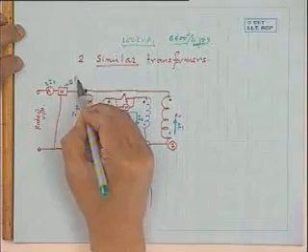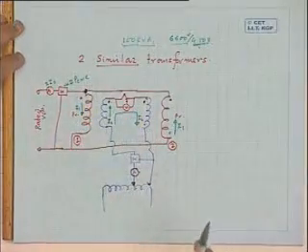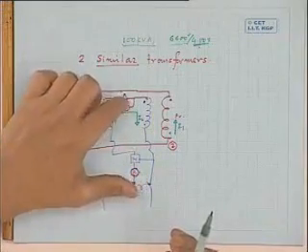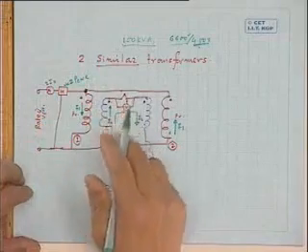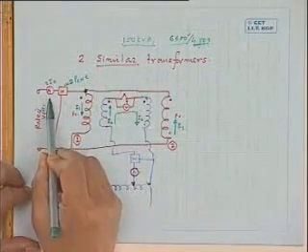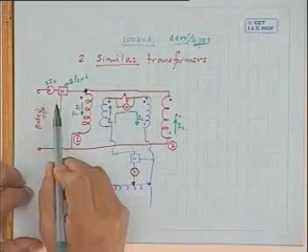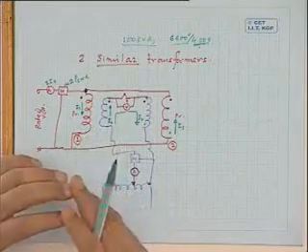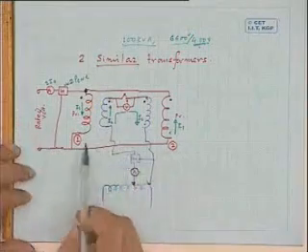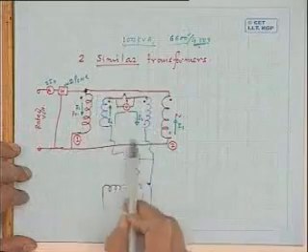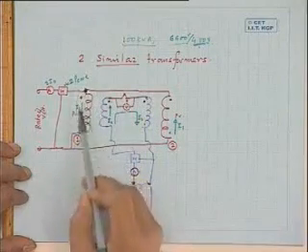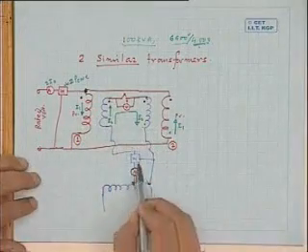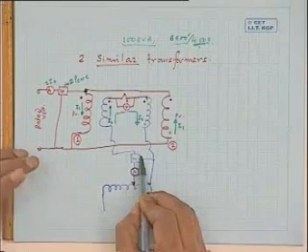And the wattmeter will read what? Twice the core loss of the transformer, 2P core. Now, what I am trying to tell, even after you connect the secondary in parallel here, like this, and apply some current here, the primary current will not change. It will remain where it was. Because there will be reflected current on the primary side of both the transformers, but they will be circulating within them. That can be easily seen by applying Kirchhoff's current law at these junctions.